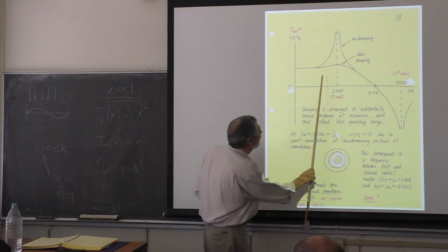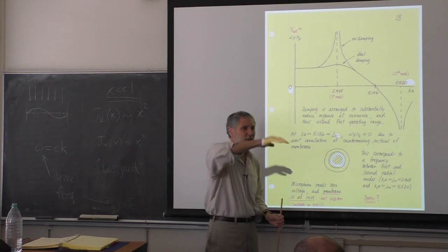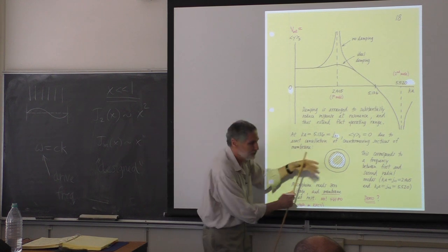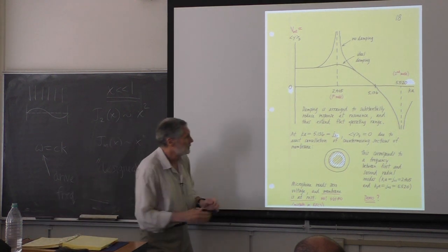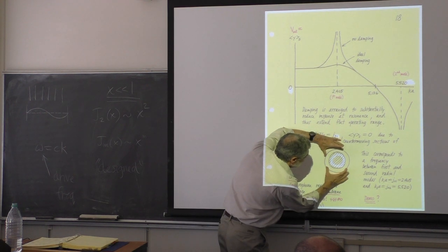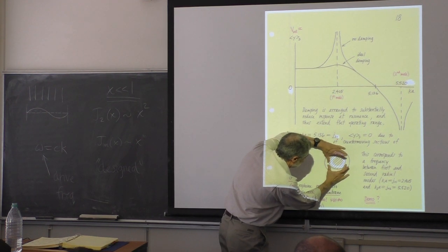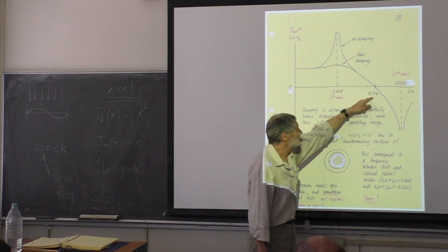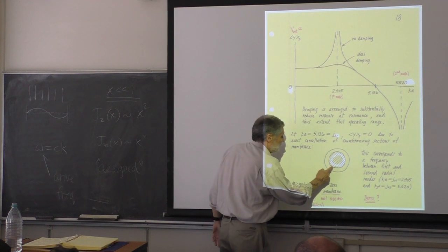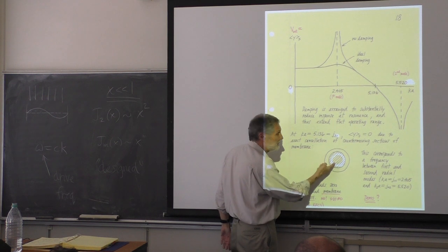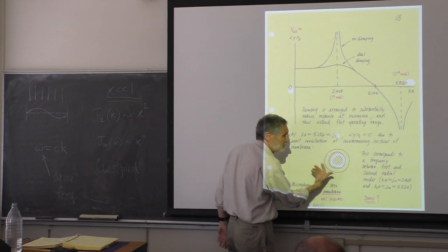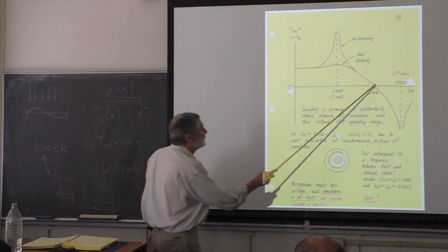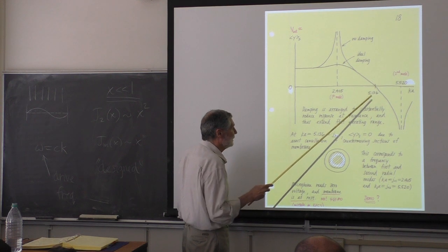Well, as we go to higher frequency here, the membrane's going like this. Eventually, there's going to be a node coming in from the boundary here. As you slowly increase the frequency, there'll be a nodal circle that comes in from the rim. And here it is at some later time. And this ka value here, which will correspond to a certain frequency, is where the average area is 0. So this is coming out, this is going in, and they exactly cancel. So the voltage is going to be 0. We're going to get 0 voltage here. This would be a great demo.